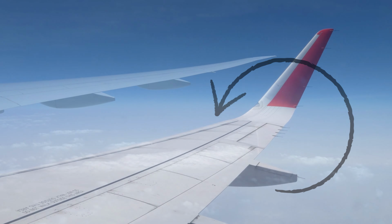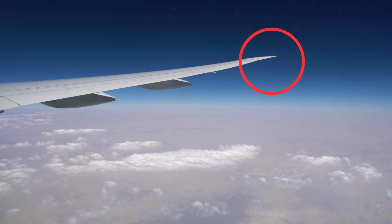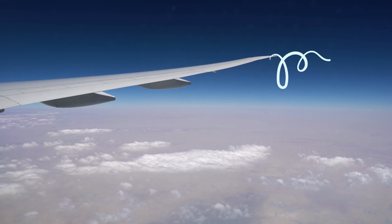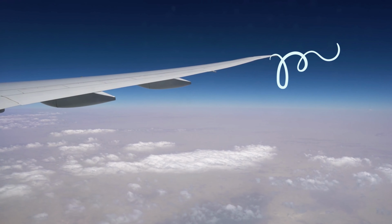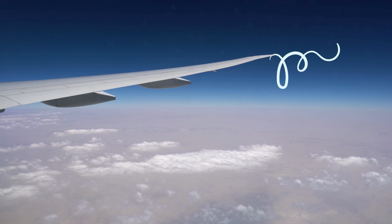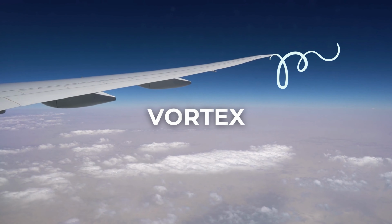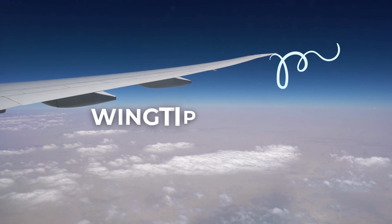So, in the case of the aircraft wing, air tends to flow from below the wing to the upper surface of the wing. The movement of air happens at the wingtip, where the airflow moves out from under the wing, swirls around the tip, and tries to enter the low-pressure region at the top. The circular motion that the air takes is called a vortex. Since it's generated at the wingtip, it's called a wingtip vortex.